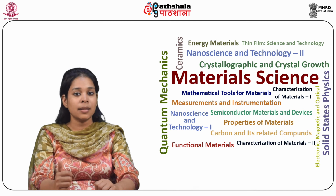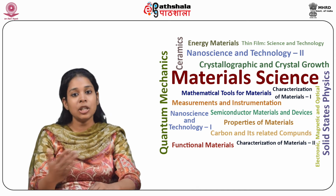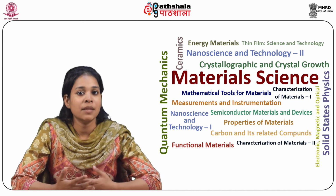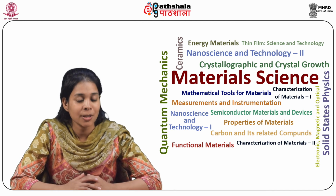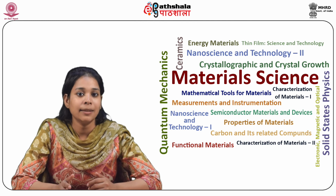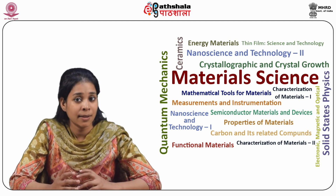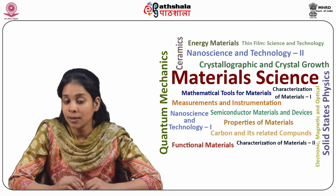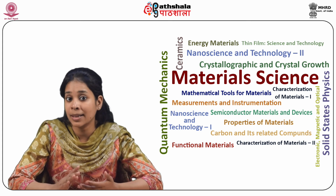So liquid phase sintering is the second type of sintering which we have read about, and in this some liquid is present during some part of the sintering cycle and the initial densification occurs due to particle rearrangement due to capillary forces. Further densification occurs by solution reprecipitation, in which the sharp corners and edges of the solid particles are dissolved by the liquid and transported through the liquid and deposited elsewhere, leading to a rounding off of the grains. This rounding off allows the grains to pack better and so causes an increase in the density. And towards the end of the cycle, the solid state controlled sintering starts, which is undesirable and should not be prolonged, which we have discussed clearly in the module.